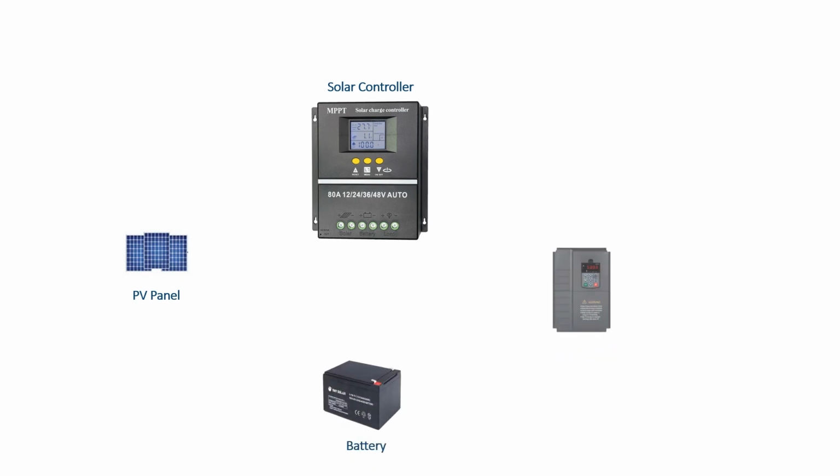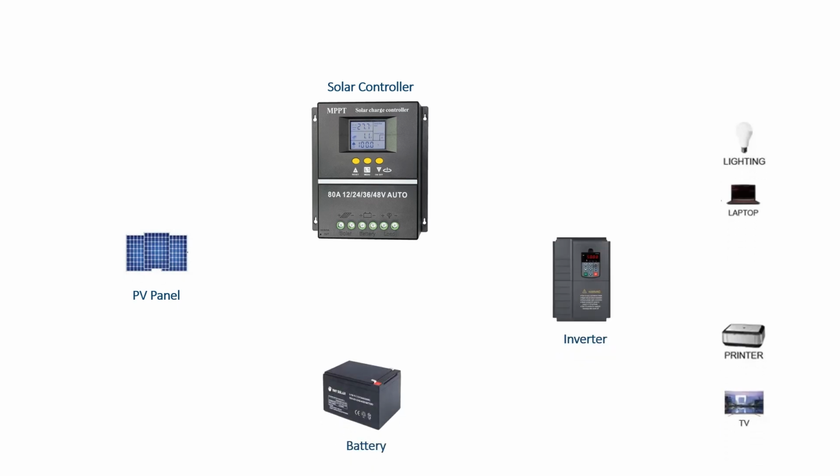Solar power system wiring connection. Broadly, there are 5 steps for wiring the solar power system. Step 1. Connect the battery. Before connecting the battery, check the open circuit voltage of the system battery. It must be at least equal to the controller operating voltage. The battery should be connected first. This will activate the controller self-protection features, and will power the LEDs to guide installation and startup.